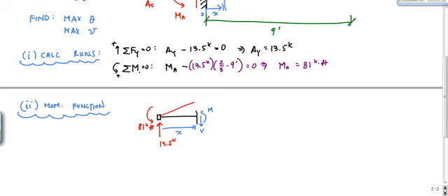And I also have the distributed load that's also cut right here, whose value I don't really know, because it's varying linearly from 0 to 3 kip per foot as a function of x. So now let me solve for M here using all these variables. I'll call this point here O, and I'll sum moments about O equal to 0. Positive is this way, and so I'll have M, what I'm solving for.